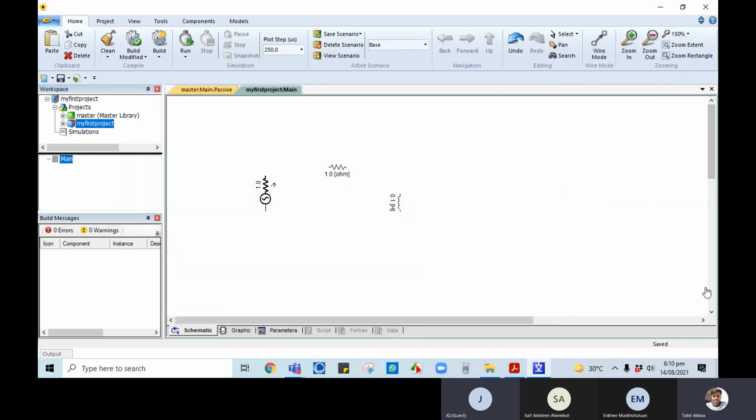Okay, great. So next move, in order to connect this diagram, just go to wire mode and then click on this, and then again left click, you can turn, and then click and then escape. When you press the escape button, wire mode will be off, otherwise it will continue. Then again, go where you want to turn, left click, and then left click and then escape.